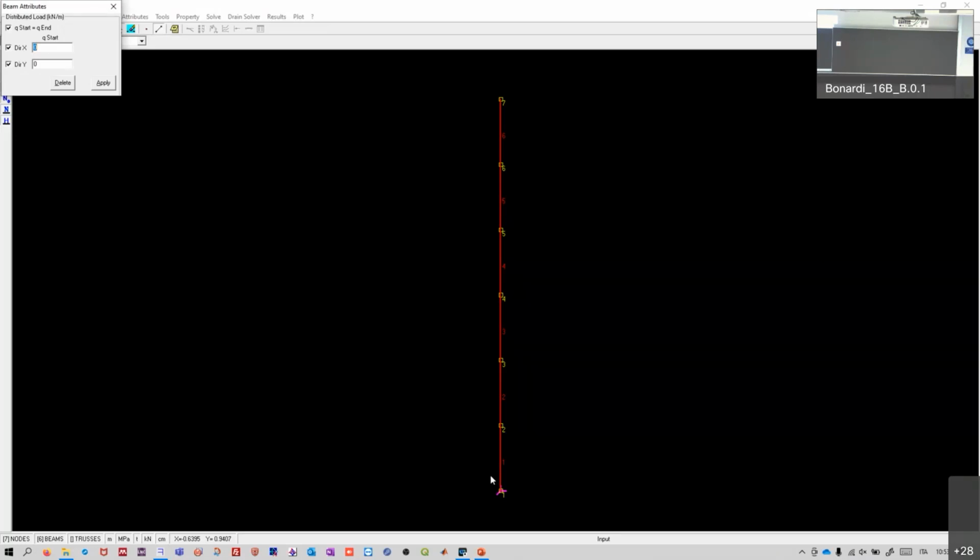The restraint here will directly absorb all the load that we provide the structure. So even if the earthquake comes from the ground, we do not apply the load at the base, because what happens is different. We have an imposed displacement at the base.